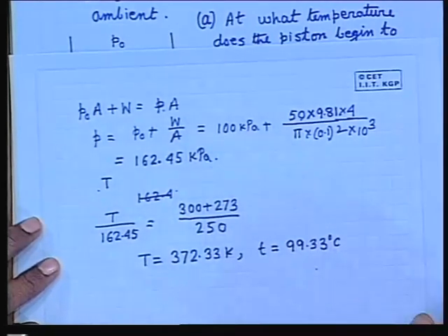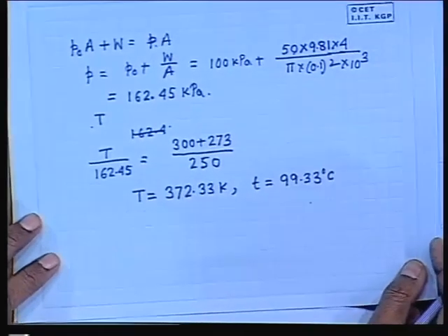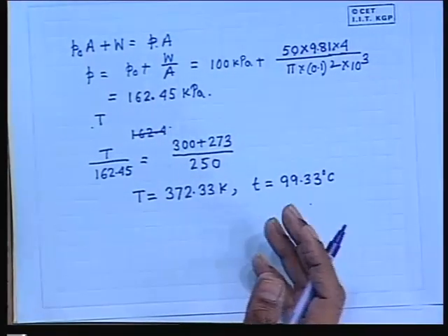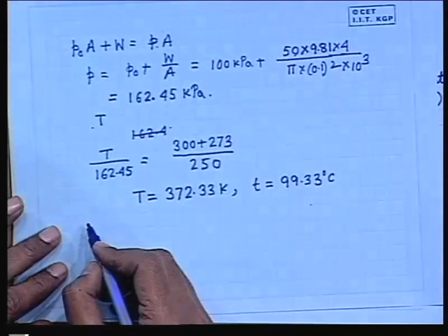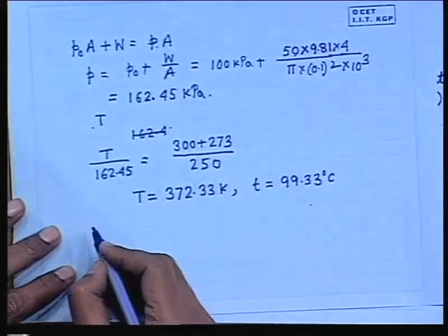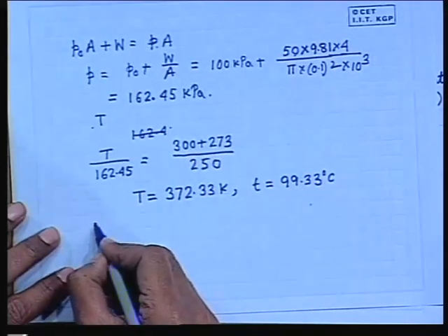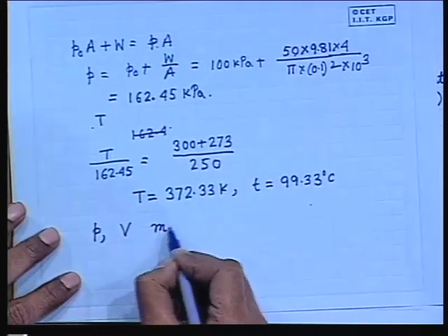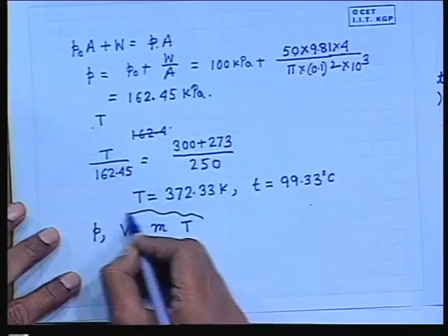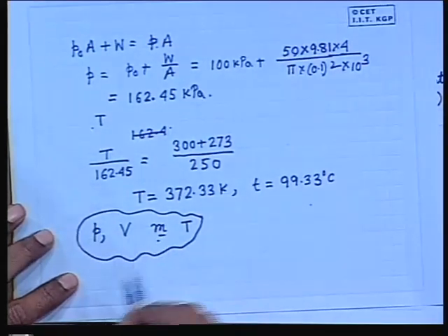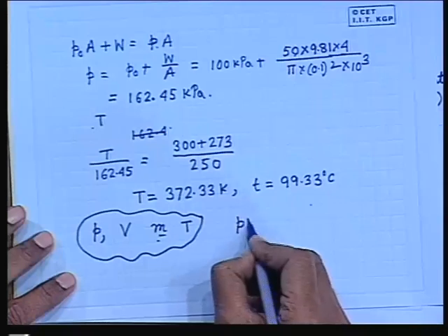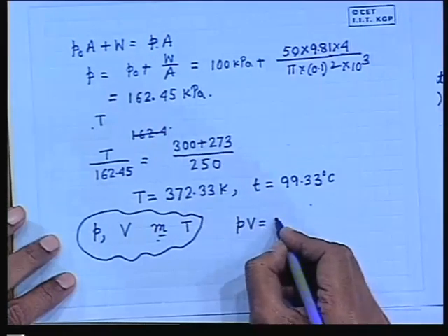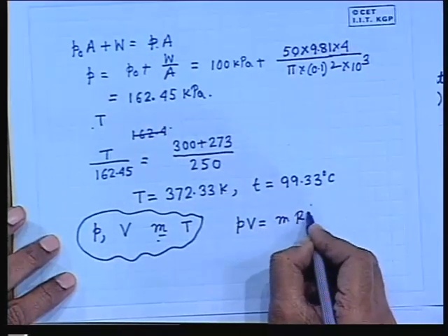Now, where from you got P1 by T1 is P2 by T2? Volume. But you are not supposed to know now, first law. So, I tell that sometimes it will be given. If it is not given, then for air, I recapitulate the earlier things. You always know that if P is the pressure, V is the volume, M is the mass and T is the temperature of a certain mass of gas M, then for any ideal gas, this is the relationship, PV equals MRT.